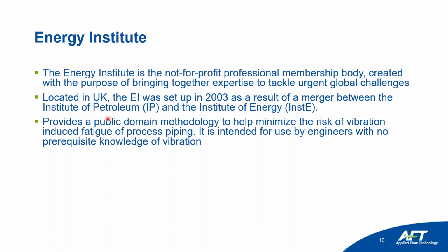It provides a public domain methodology to help minimize the risk of vibration-induced fatigue of process piping. It is intended, and this is very important, for the use of engineers with no prerequisite knowledge of vibration. So if you don't have experience in vibration, you can use the guide to help you solve a problem.